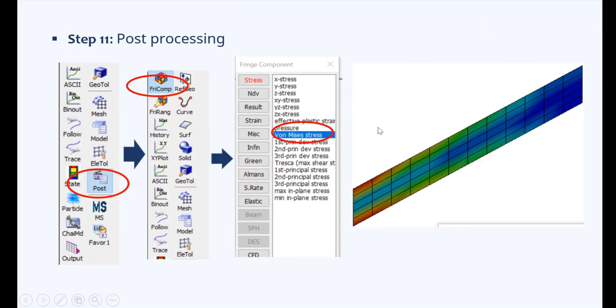And again, if you want to see more clearly the damage and where the stresses are high, you can do that. For that, you have to go to the Post option and click on Post. It will show a list of subtools. Here you can see Fringe Component, History Variables, and all these things. You can obtain the response parameters from all of these. Go to Fringe Component, which will basically show the fringe plot of these different parameters.